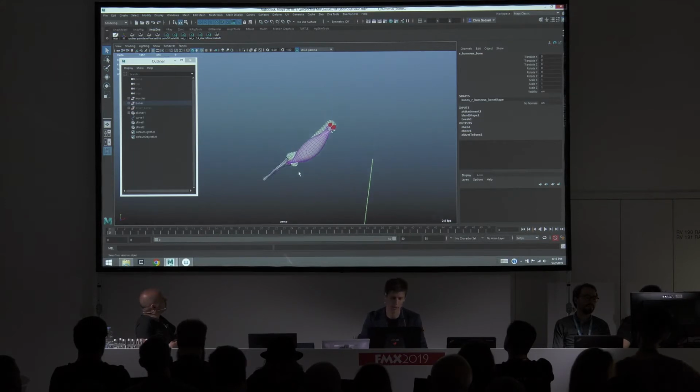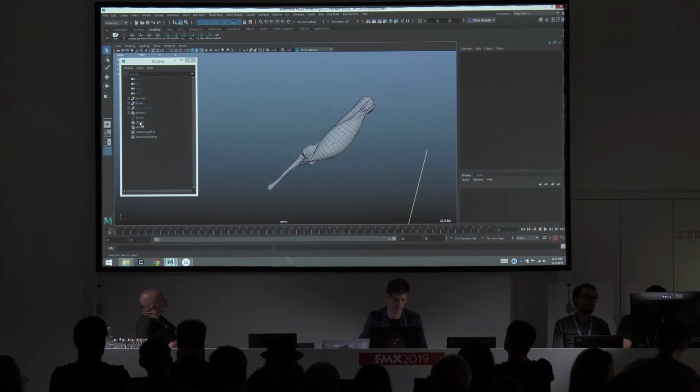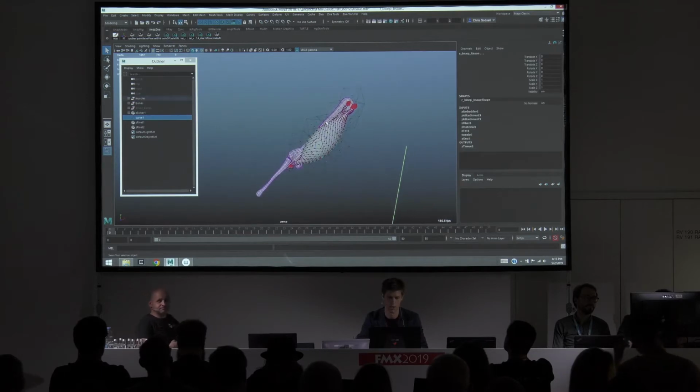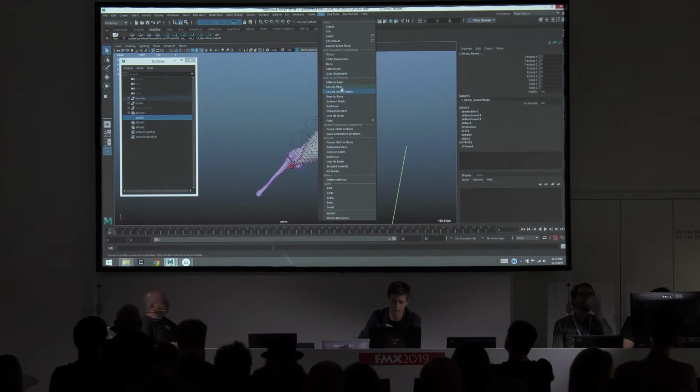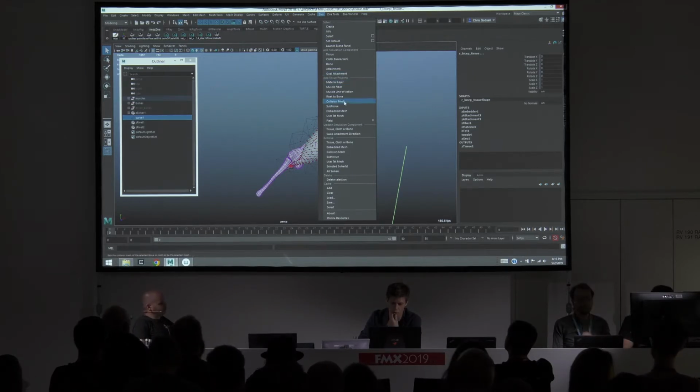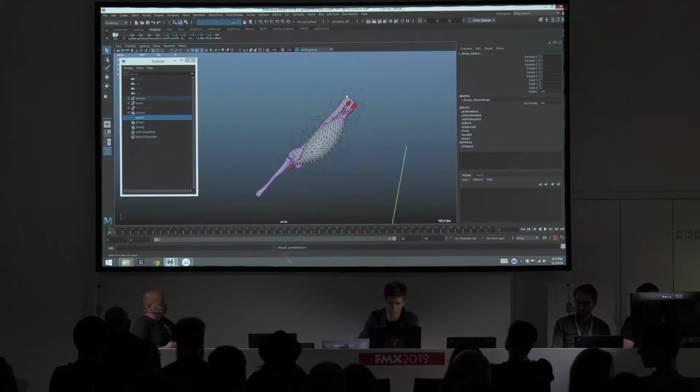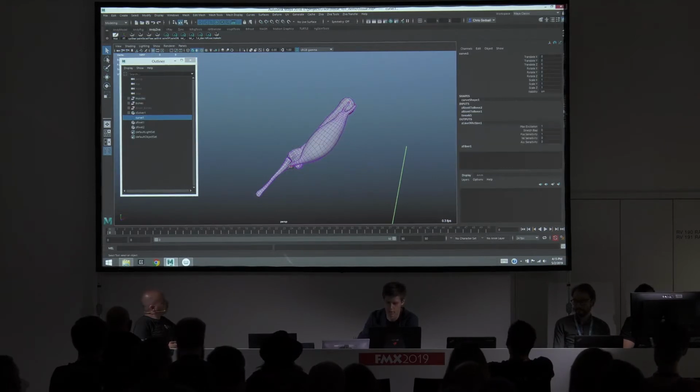And now I'm going to connect that curve to the tissue. And the mechanism we use to compute how much firing needs to happen is called line of action, or muscle line of action. So with those two objects selected and I choose muscle line of action, you'll see that we get this line of action node here now. So you can choose to fire the muscles based on position here. So this is position of the endpoints.